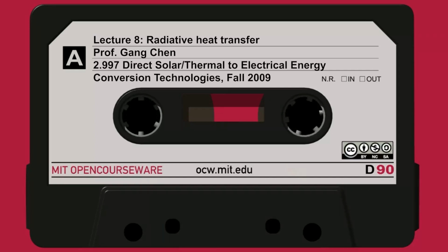Again, by doing this, I have a universal function that gives the fraction of energy with wavelengths between 0 and lambda for any temperature T. So if you give me a temperature, I look at the wavelength, do that multiplication, check the table, and usually quickly you find it. That's the integrand, the small f, as a function of lambda T written in micron Kelvin, and here is the integral, the fraction of energy between 0 and lambda T.